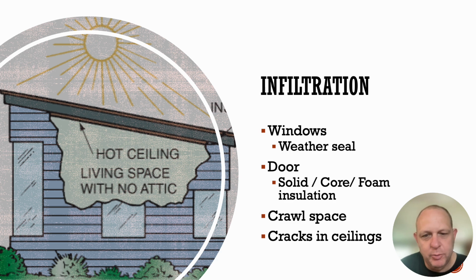Well, like I said before, humidity is a huge concern for us in the wintertime and also in the summertime. I had an instance of a crawl space that was open, that they were sucking air out of the crawl space and then blowing it into the house themselves. We had a dew problem, a moisture problem on the windows. They thought it was a window problem. The window guy came out and replaced the windows, and it happened to be a moisture problem from the moisture in the crawl space. So the way to prevent that from happening, we suggested that we put a vapor barrier down in the crawl space, but also that we tie the ductwork into the actual piece of equipment so we're not sucking crawl space air into that.